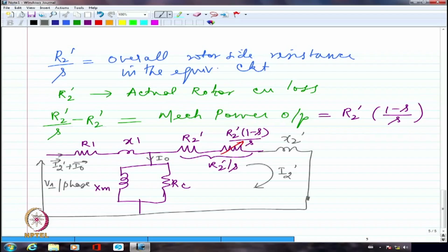If it is star connected, we will have the line current equal to the phase current. If it is delta connected, we will have line current equal to √3 times the phase current. Whatever we are doing is per phase. Everything will be converted into three-phase line or phase quantities by multiplying by the appropriate factors. That's it. Yes.